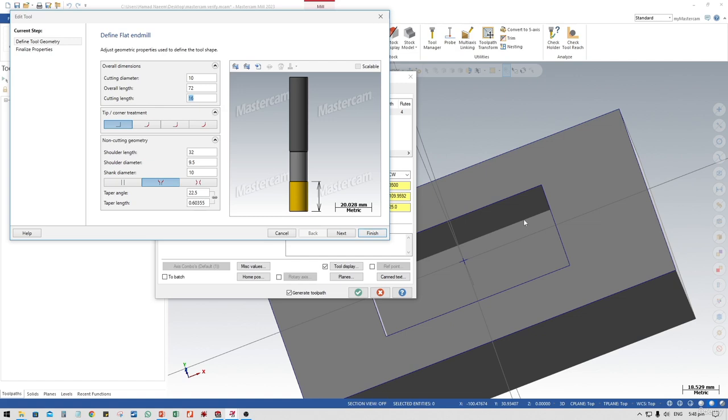You have to select the appropriate tool for your operation. If your cutting flute length is smaller and the depth the cutting tool has to reach is very deep, the cutter will suddenly break or it will damage your workpiece. So make sure you set your cutting tool properly, or select the recommended tools.